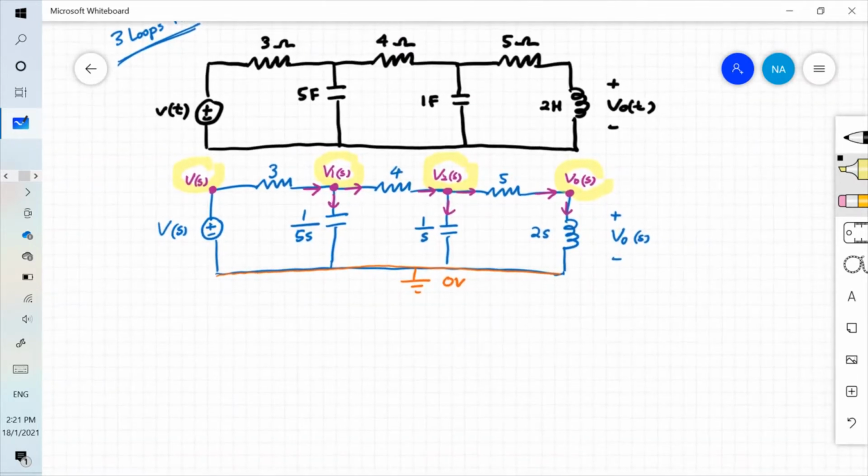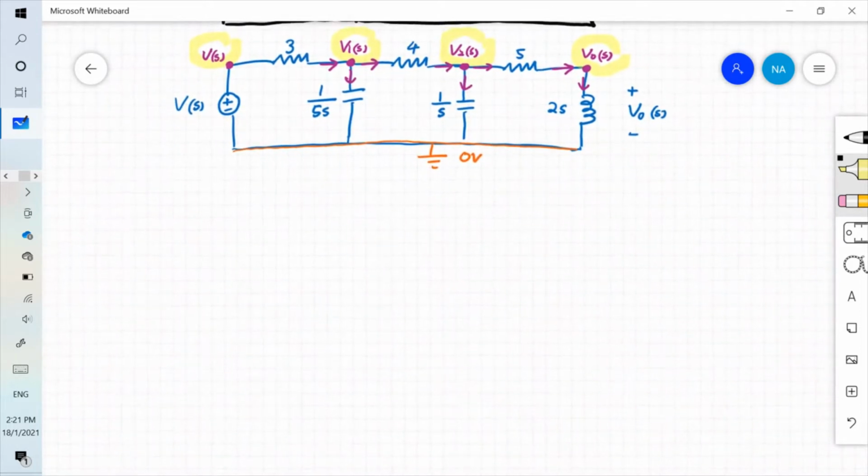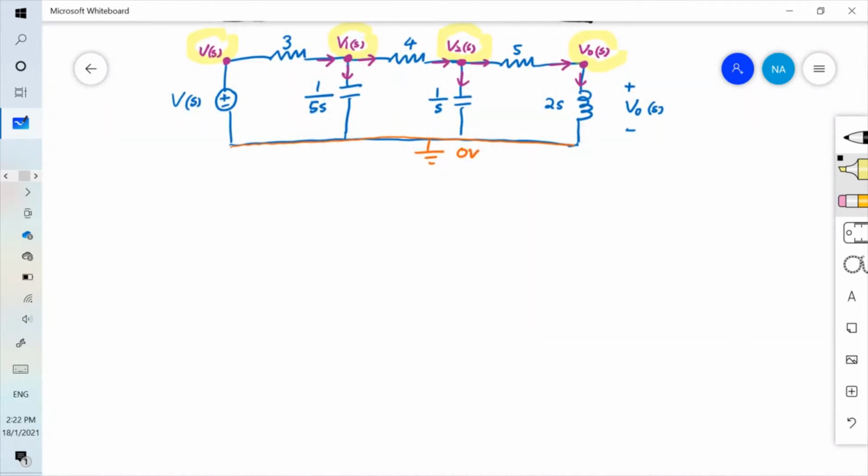next one, we're going to come up with the node equation. So we're going to do node number 1. Node 1, you have 1 current in and 2 current out. Okay, so on my circuit, I have actually drawn that yellow or orange line, which denotes the 0 volt grounded line because it is connected to the negative supply. So it is denoted by 0 volt. Okay, so back to node equation. Node number 1. 1 current in, 2 current out.